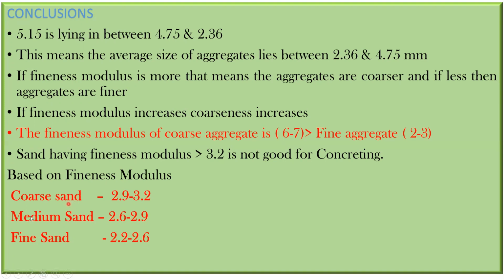So what is the practical application of this? The practical application of this is when we do the mix design, that is in chapter 3, we are going to check all these things, what is the fineness modulus, and based on that we are going to do the calculation, and based on that our mix design will be prepared. So these are the uses of fineness modulus, and with the help of this the mix design is going to be carried out later.